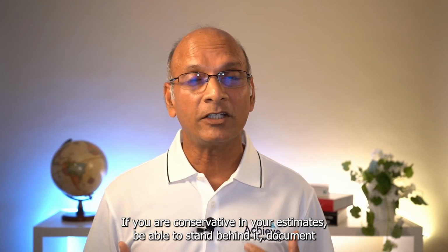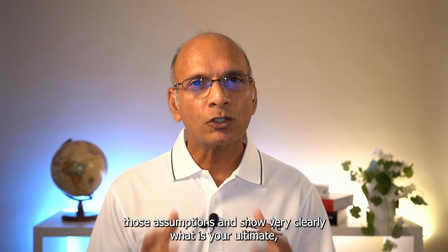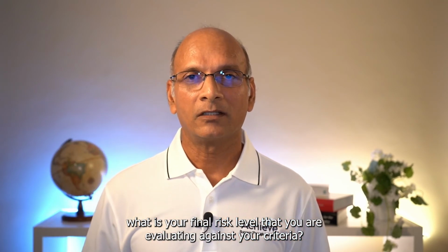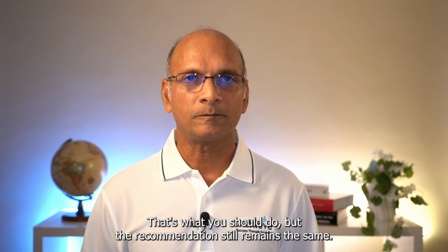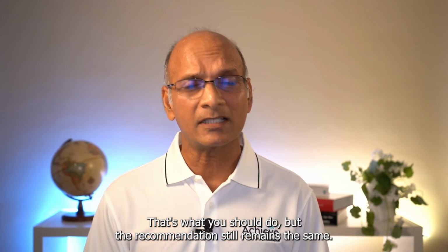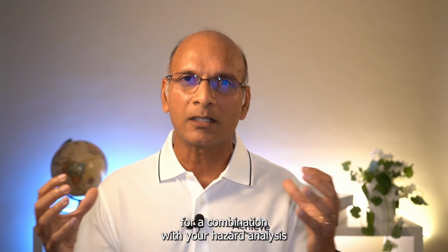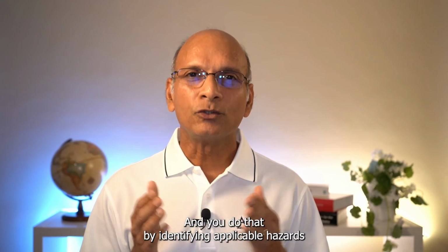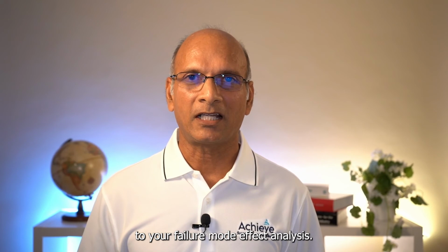If you are conservative in your estimates, be able to stand behind it, document those assumptions, and show very clearly what your final risk level is that you are evaluating against your criteria. That's what you should do. But the recommendation still remains the same. Do not mix the two, but prepare your FMEA so that it is suitable for a combination with your hazard analysis, leading to a risk assessment and a risk trace matrix, for example. And you do that by identifying applicable hazards to your failure mode effects analysis.